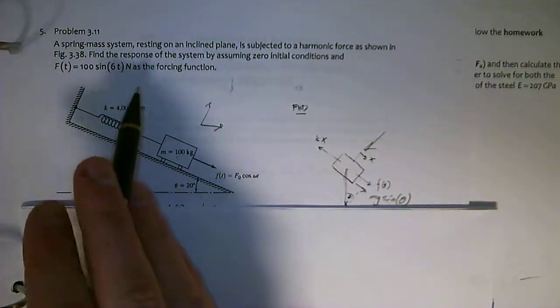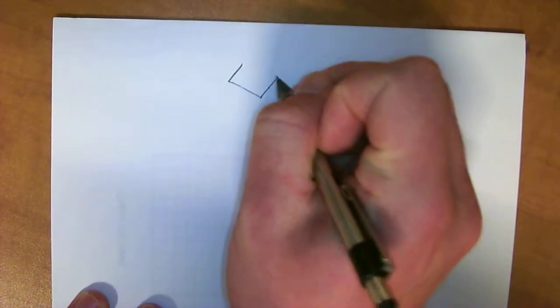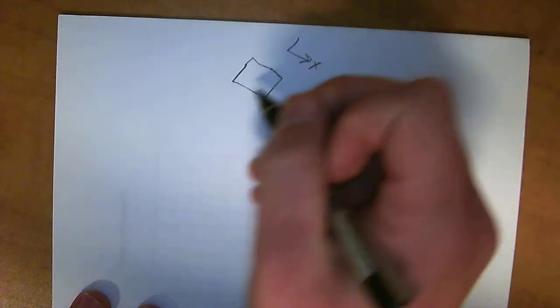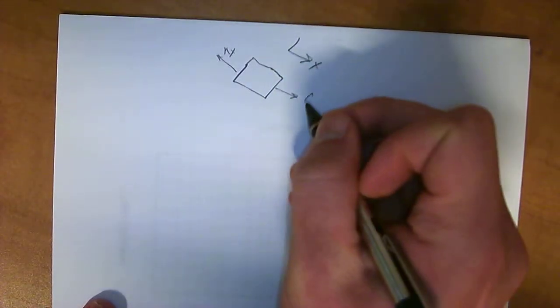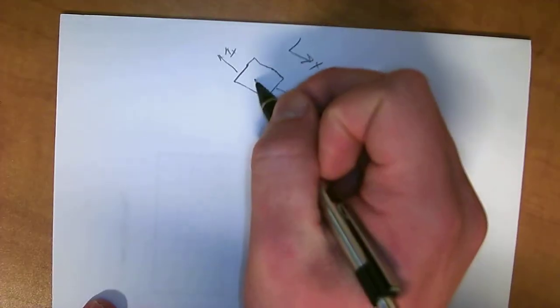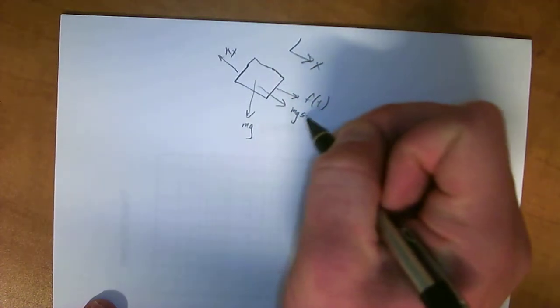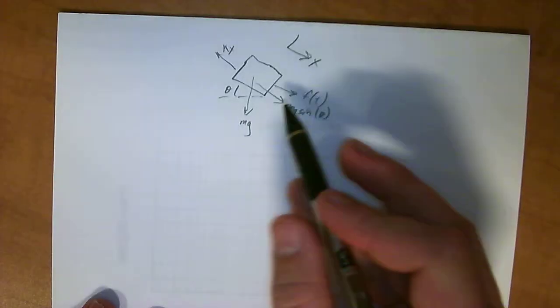So if you can go ahead and write down these values, I'm just going to skip right into the problem. When you're looking at this problem, I'm going to draw the free body diagram. You've got a block right here, and we're going to measure x in this direction, so that even though there's an angle of theta, we don't really care about it that much. We have kx right here, we have f of t, the forcing function, right here, and then we also have mg right here. But that will translate into a force in this direction of mg sine of theta, because you're sitting at an angle of theta right here. Okay, so that's our basic setup.